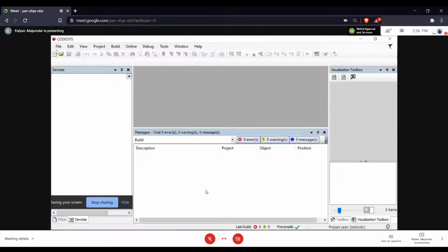Your PC is just acting as a development system, a development tool where you develop the code. Not only do you write the code, you compile it, you test it. In case there's a problem, you debug it. The entire development process is done on this particular tool. And once you have this code which is functional, which is proven, you simply download it to the target system. The target system is a microcontroller which is going to execute this particular code finally.